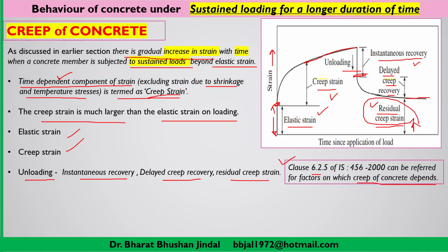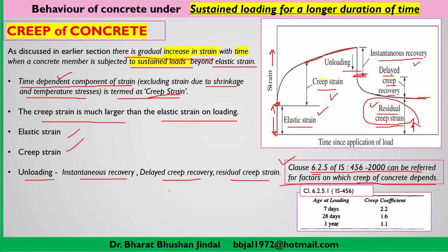On what factors the creep of concrete depends, you can go through and read clause number 6.2.5 of IS 456. In that IS 456 you will find a table under clause number 6.2.5.1, where it is clearly mentioned, in the first column, age of loading and creep coefficient. You can observe here that at 7 days the creep coefficient is 2.2, and at 1 year you will find that the creep coefficient is on a decreasing trend.